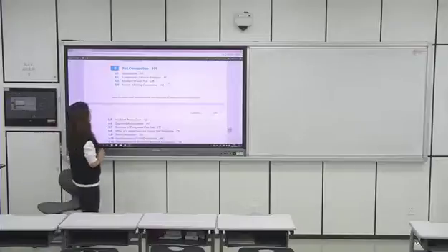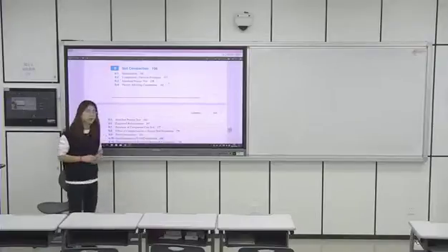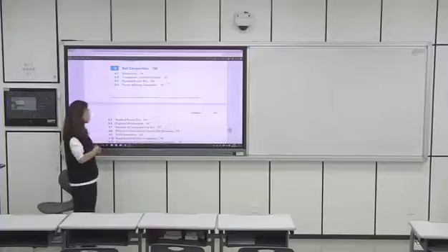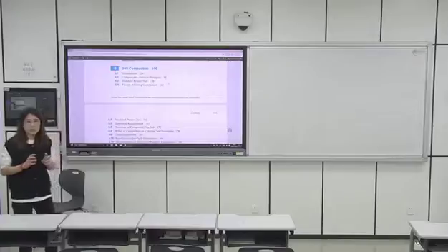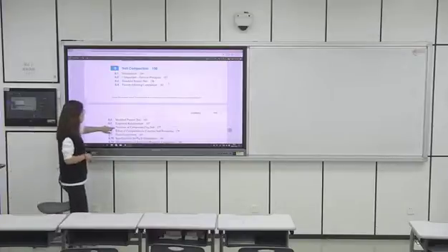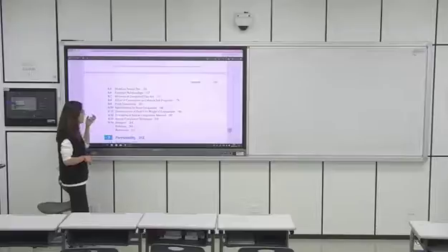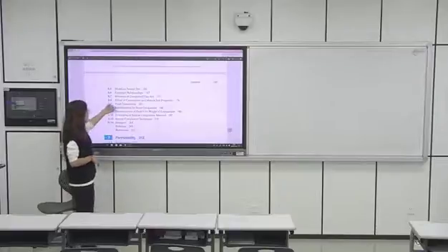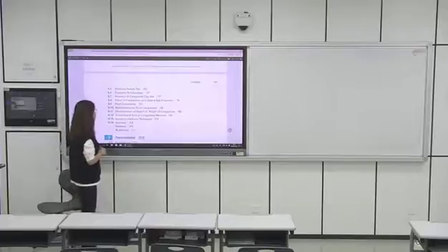And compared with the standard Proctor test, there is the modified Proctor test. The modified Proctor test just enhances, or improves, the input energy compared to the standard Proctor test. And then we learned some empirical relationships for compaction. And then field compaction, we introduced some machines to do the compaction in the field.